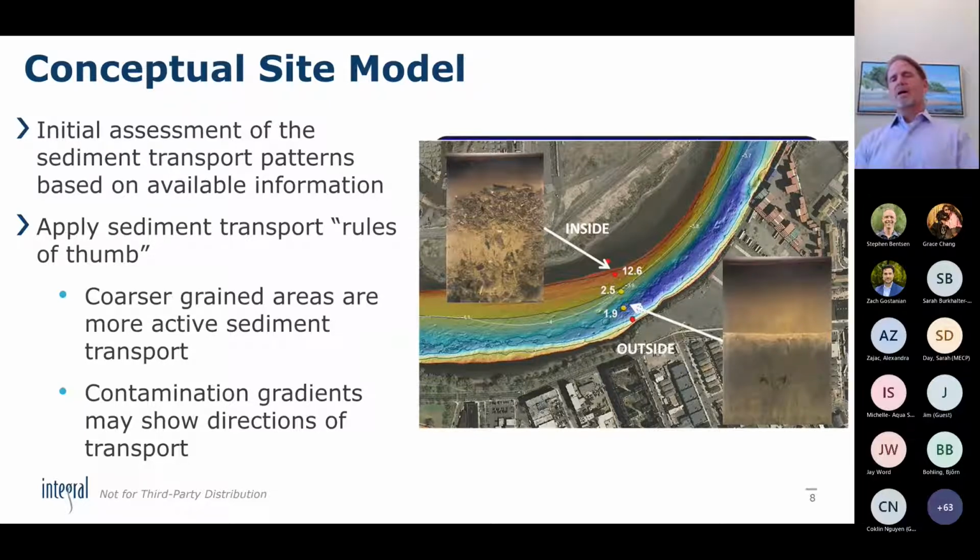It's only going to deposit out in a low energy area. Whereas if we start looking on this bend out here, on this outside bend of the river, we don't see any of that leafy material. We're talking 100 yards away here. This is much more consolidated, stiff silt and clay that is very difficult to erode. So this part of the river is essentially scoured down to the stable sediment bed here.